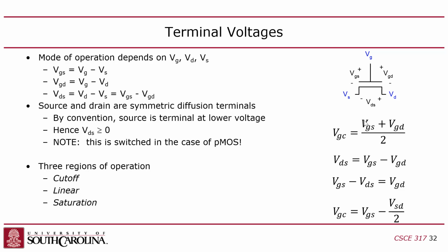Because this one's connected to VDD. So this is the source, and that's the drain. But if you look at the pull-down transistor, this is lower voltage. It's connected to ground. So this is the source, and this is the drain, which means that the source and drain are flipped, right?